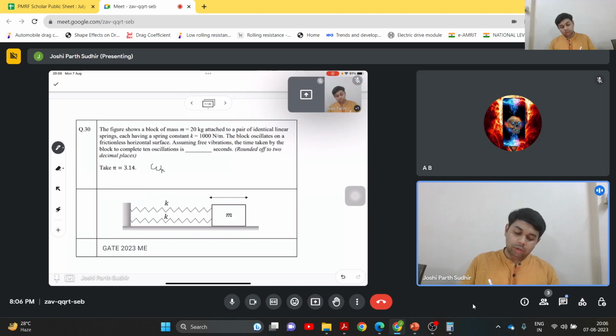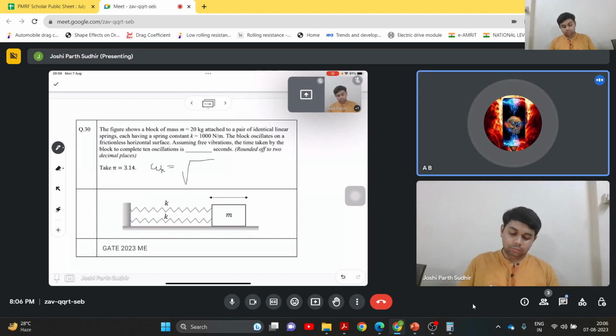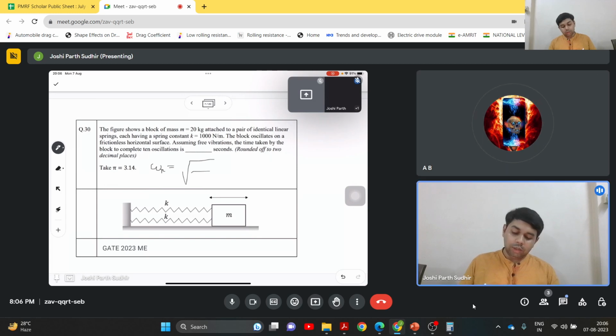So omega n is what? Root over k upon m. Yeah, so here there are two springs in parallel, right? So now they will add up, right? Yes, sir. So it will be actually 2k by m, right?